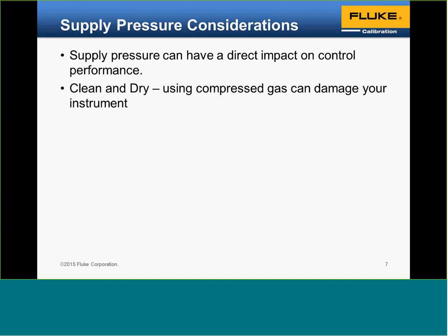Gas that has not been sufficiently dried and cleaned can damage the instrument. And air will generate moisture or water in the media, which will possibly cause corrosion or even a mess. So it's always best to make sure that you're using clean, dry air or nitrogen gas media.